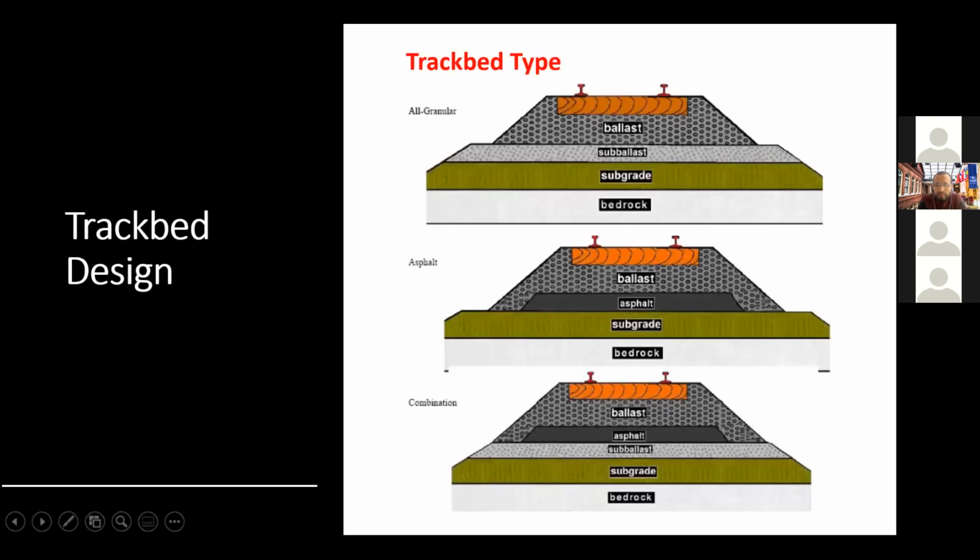I often find that having heavy finite element modeling for this sort of work, unless there is a necessity from a subgrade point of view, sometimes you tend to go way over budget. So that's why in practice, people always tend to rely on empirical equations, experience, as well as semi-empirical approaches, if need be.